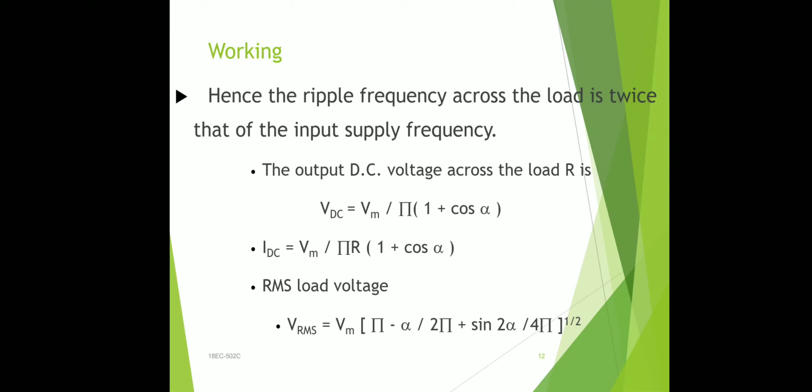After the positive cycle or negative cycle, whichever SCR is conducting will be turned off immediately with the phase reversal of the input. Again, the other thyristor will come into conducting mode after the delay angle.